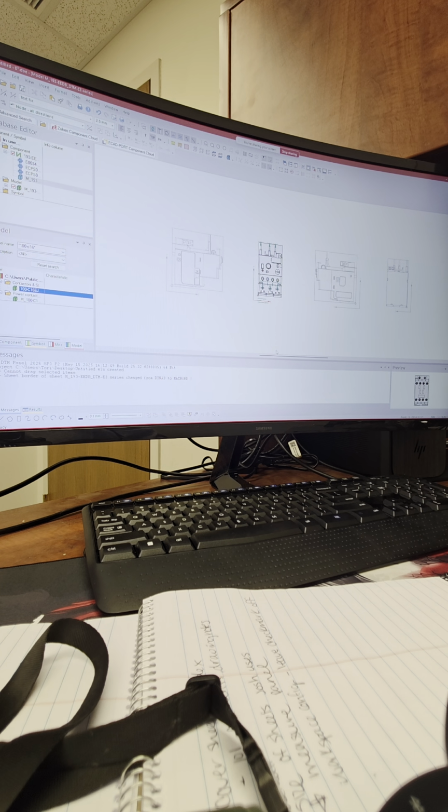is set up using slot points and a mounting description. Now, just to show you the principles behind these things, in your model device structure on the left side, expand that little model name. So not the library, but your little temporary editor up on top. Under model, expand that so you can see the full contents of it. Whenever you import a step file, like in this case, there was a step file, there was a model for this thing. When the step file is imported, the import process creates these side views, bottom views, top views, etc. that you see here grayed out.